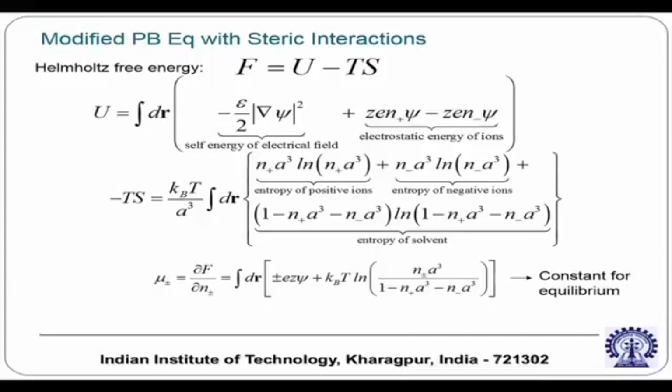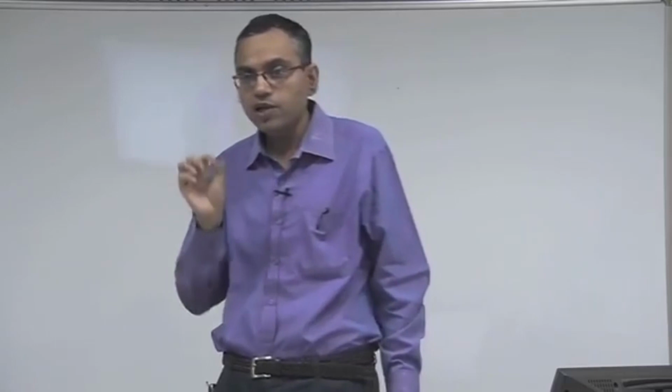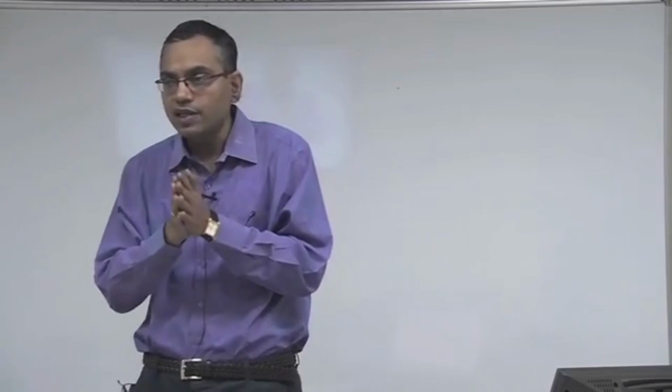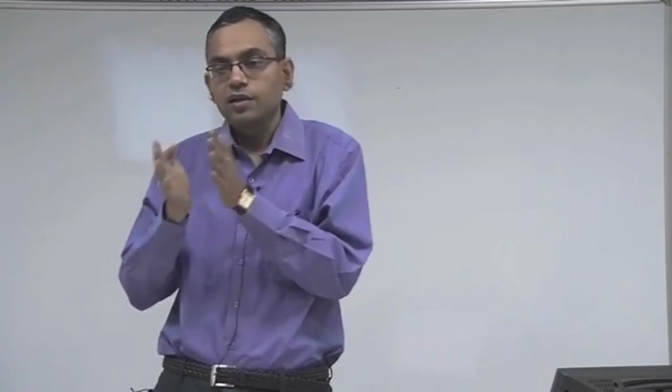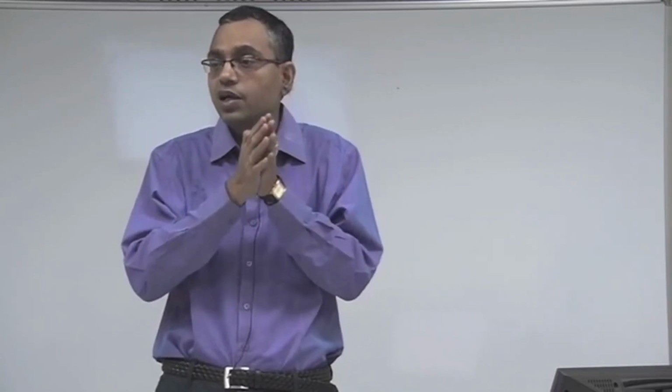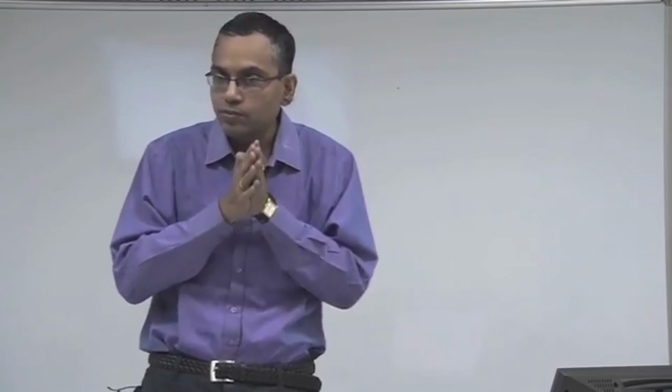Let me answer this question more carefully. One has to have a very rigorous thermodynamic background to appreciate that. When do you use Gibbs free energy and when do you use Helmholtz free energy? It depends on the context. If you are interested in coupling it with transport phenomena, we commonly use the Gibbs free energy. The reason is that there you are talking about enthalpy, which deals with the thermal energy of a flowing system.